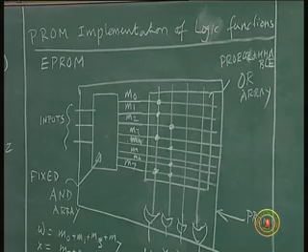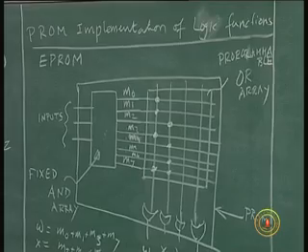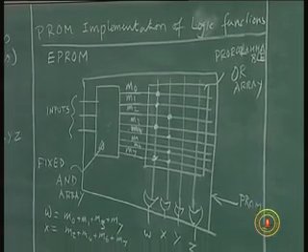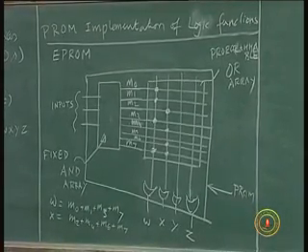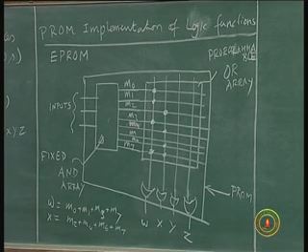ROM is the truth table etched in silicon, a hardwired truth table. PROM is a truth table whose output can be changed as required. And erasable programmable read-only memory is a programmable read-only memory whose programming I can erase and reprogram for different applications, for changing a configuration, or making a correction. How do you erase it? There are technologies. You can erase it by shining ultraviolet light, called UV erasable technology, or electrically erasable, double E.